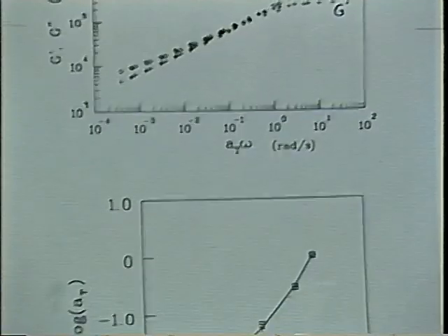And that was quite surprising, having a phase-separated structure, which doesn't show any significant effect on the shifting. Often phase separation changes the shifting coefficient, and then you cannot apply time temperature superposition, and you can use that really as an indicator of a phase transition in the material.